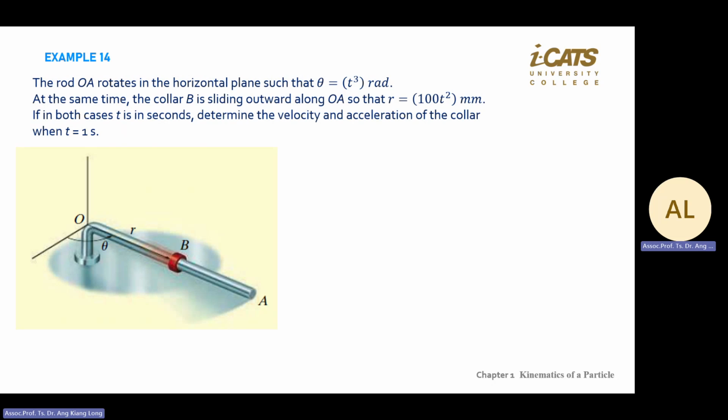So you write theta equal to one equation, R equal to one equation, then differentiate for theta dot and theta double dot. This is mathematics. R is the same, R dot, R double dot. Once you differentiate, substitute back into these four equations. Or even I can say only two equations here, but I mentioned four because it's clearer when you substitute.